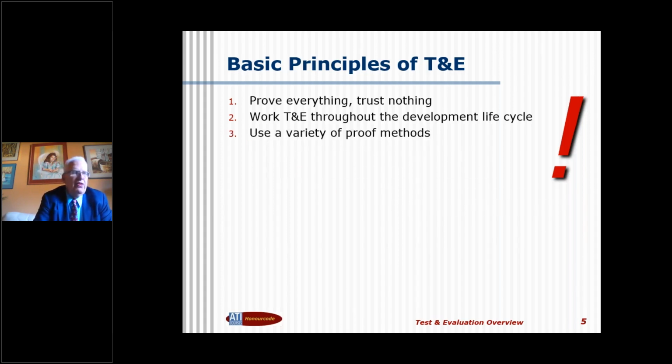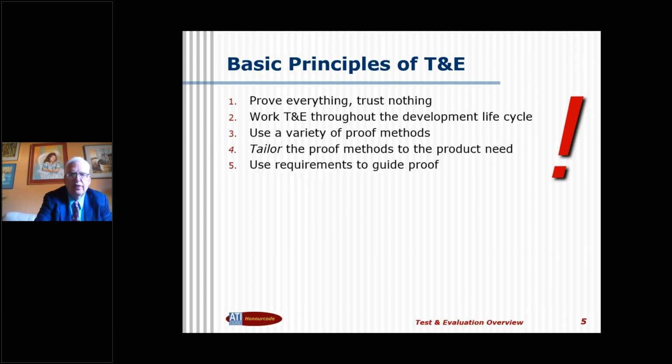Use a variety of proof methods. We'll talk about test, analysis, demonstration, inspection, or primary proof methods. Tailor the proof methods to the product need. For various systems, you might have more or less testing in various parts of the life cycle. Use requirements to guide the proof.